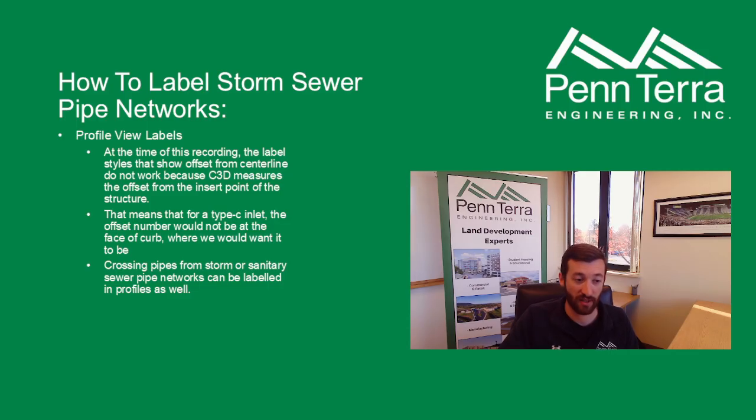So on a round sanitary sewer manhole, this works okay, but on a rectangular inlet box, especially a type C inlet box, we may not want that offset to be a foot off the curb, for example. Generally, we would probably want that offset to be at the face of curb. So we don't want to use those styles with our storm sewer pipe networks. If it's something that you are required to show, you could always edit label text on your labels and type that in manually if you'd want to.